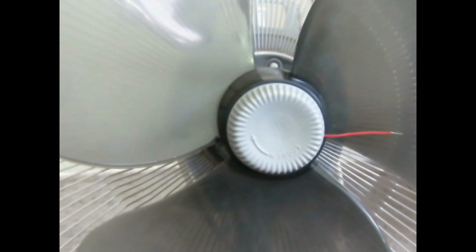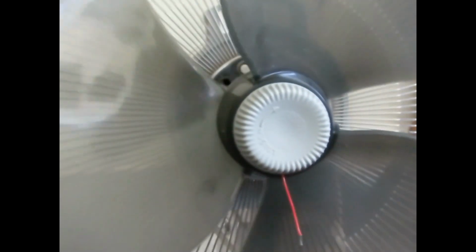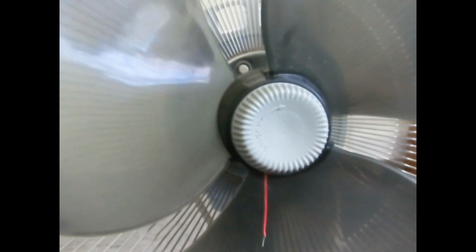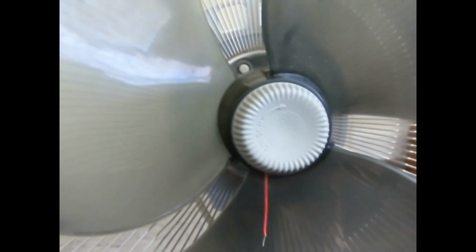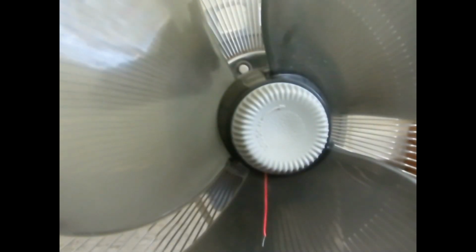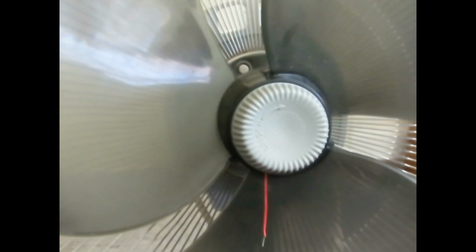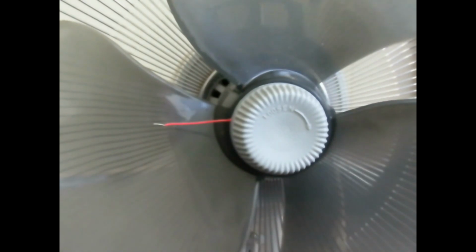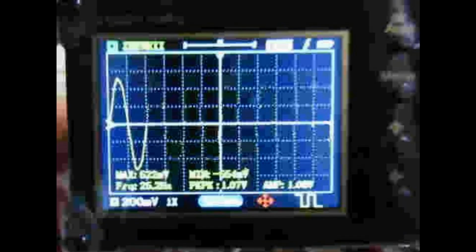When we rotate it again to 270 degrees, or negative 90 degrees, you'll get three-quarters of the cycle, and you'll be down on the negative peak voltage. When you rotate it again, it will come back to 360 degrees, or 0 degrees for the next cycle. So that is one full cycle of that fan spinning, and you get that sine wave. You keep spinning it, and you get one cycle after the other, as seen here.